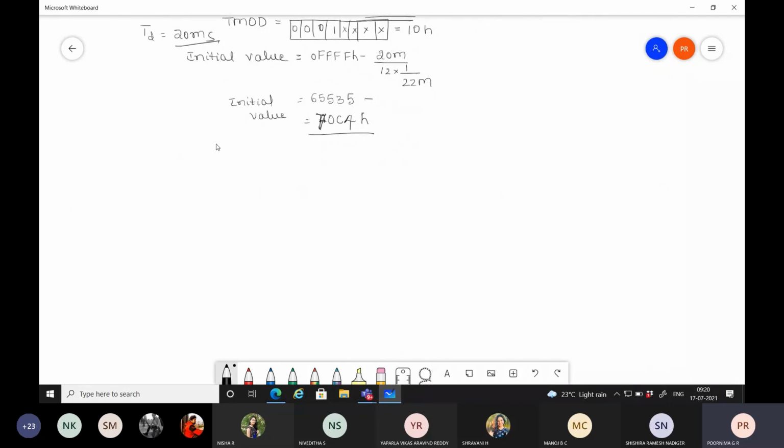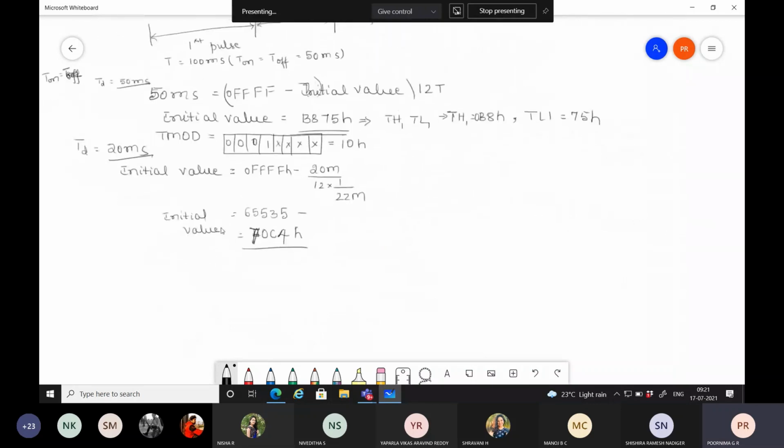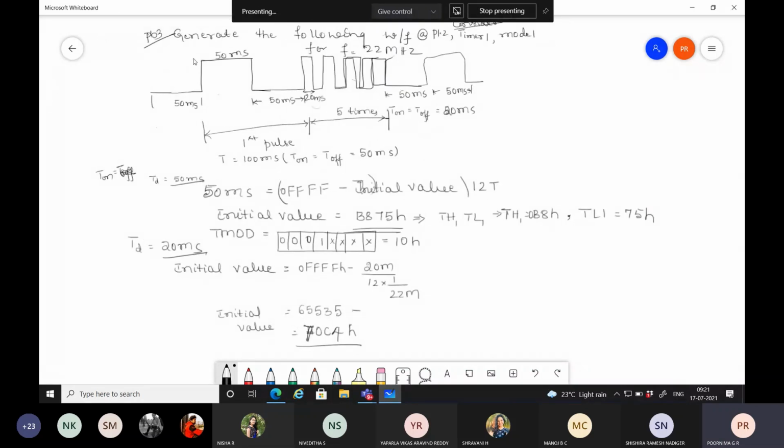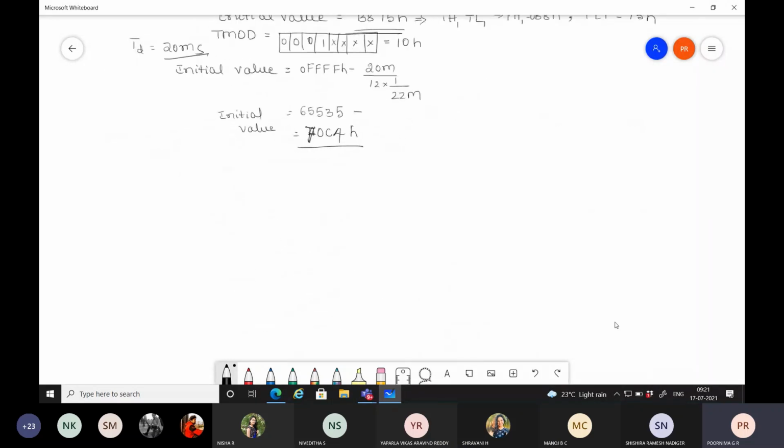When we look at the waveform, the initial value to be sent to port 1.2 pin is a high value. So only a single pin is involved, and it need not have multiple bit values like the previous problem we have done. So you can set that particular pin itself to a high or low value. So set B. Program.